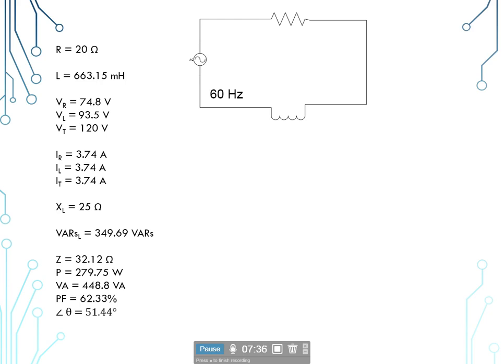Now we have our list of all of our calculated values. We're ready to go out to this circuit and make live readings with our meters and compare them to what we calculated to see if they're close. If they're close, look somewhere else. If not, dig a little bit further into that circuit. There is an issue there.